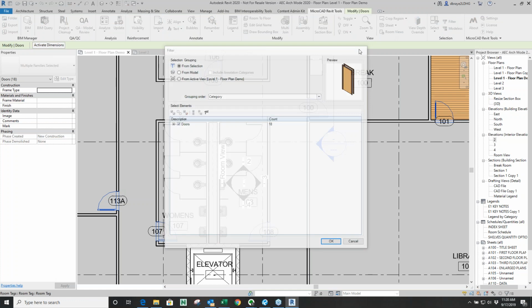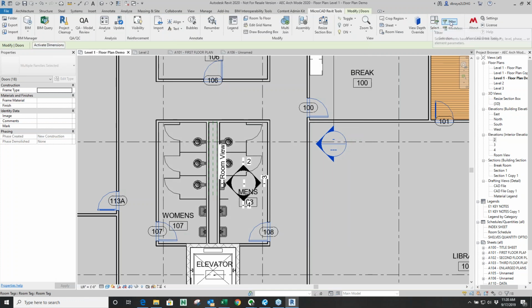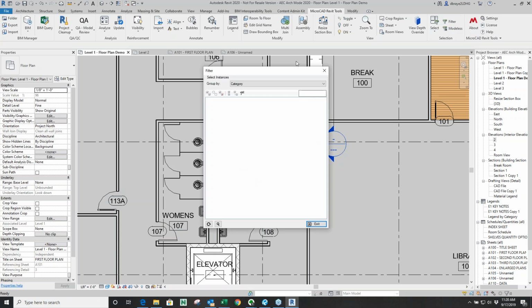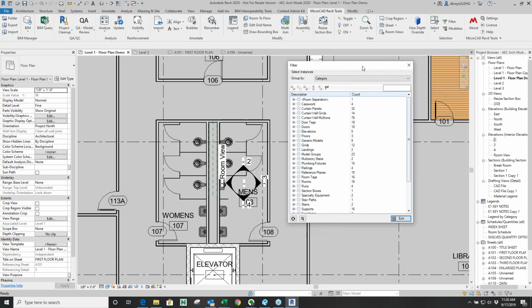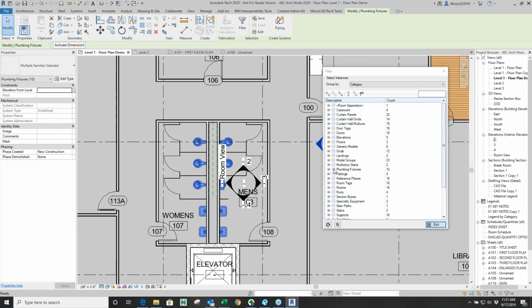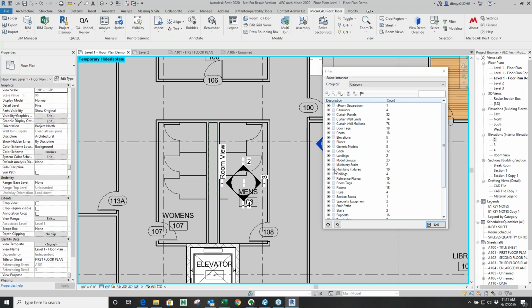Another filter one is, let's see here. Let's do model list. Now, one thing I like about model list is that this particular dialog box can stay open, and you can use other tools while it stays open. So at any point you need to quickly select, say, plumbing fixtures, you just select that. So say I can do HH. Now all of my plumbing fixtures have disappeared.